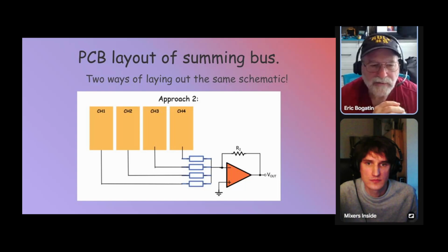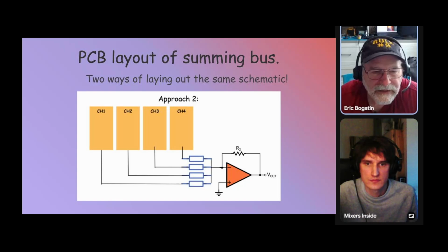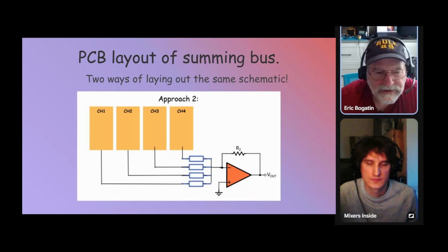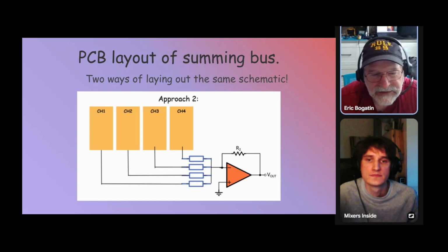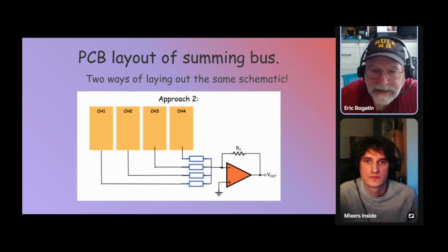There is the problem of, what you're referring to is the fact that at the inverting input there's some capacitance in the traces to the ground plane underneath. In this case, you have it DC coupled, but if you have it AC coupled, there will be some capacitance between the traces and the return. If you're trying to keep that capacitance low, then keeping the traces short, like you have here, is exactly the right thing to do.